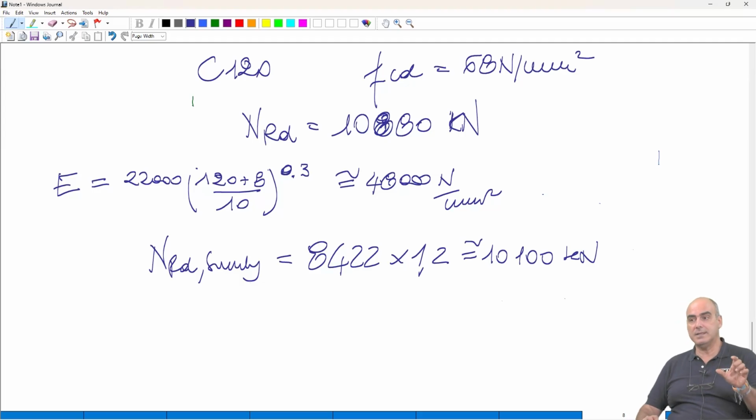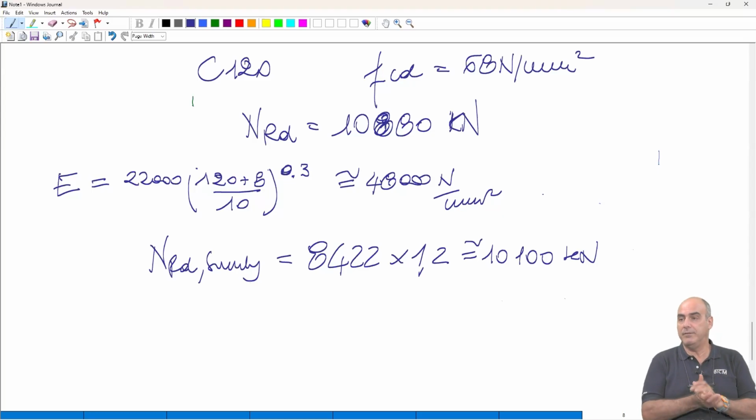So your cross-section reduction cannot be dictated by the proportion of increasing strength, but it has to be dictated by the proportion of increase in stiffness. Because if you go for slender columns and higher strength concrete, the buckling mode can prevail over the bearing failure mode.